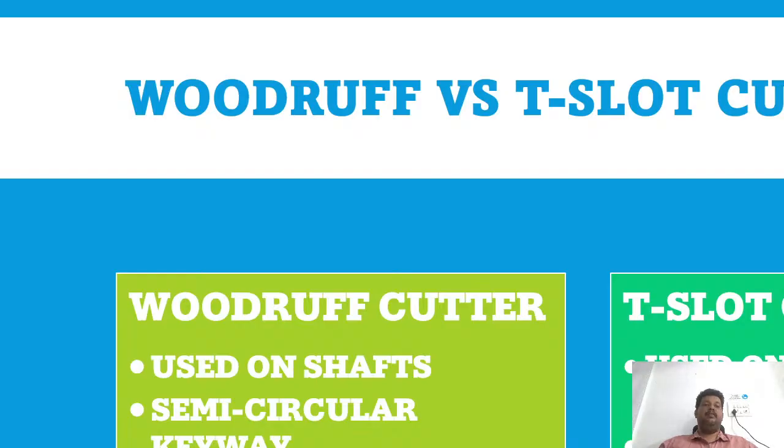Let's understand clearly. First, the Woodruff cutter. This is used on shafts to create a semicircular keyway, which is used to lock components like gears or pulleys. And one advantage is it can directly plunge into the material. Now, the T-slot cutter. This is used on flat surfaces like machine tables. It creates a T-shaped slot which is mainly used for clamping. And very importantly, it cannot be used directly. You must first create a straight slot and then use this tool to widen the bottom.